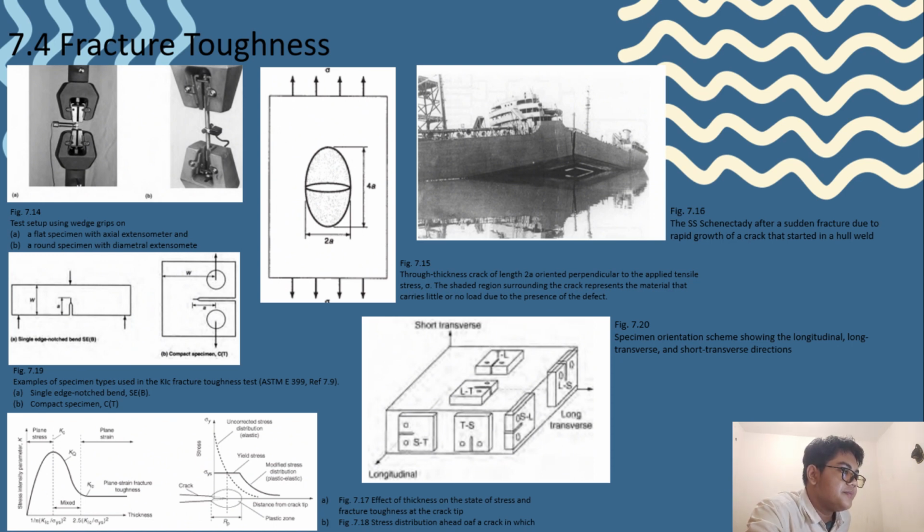Segregated impurities and intermetallics that lie in the planes represent an easy fracture path, and the toughness is relatively low when the crack plane is perpendicular to these weak planes. The delamination and crack tip blunting or stress reduction can occur, effectively toughening the material. On the other hand, when the crack plane is parallel to the plane of these defects, toughness is reduced because the crack can propagate relatively easily.